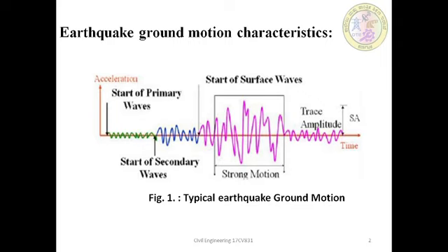It is a graph of the ground motion, such as acceleration, velocity or displacement of the ground, with respect to time during the earthquake. As the P waves travel faster, they arrive early at the location. S waves, which are body waves, arrive late and create more violent shaking. Further, the surface waves are generated at the surface only after the S waves arrive and provide a combination of wave motion. The shaking will be the most violent at this instant.